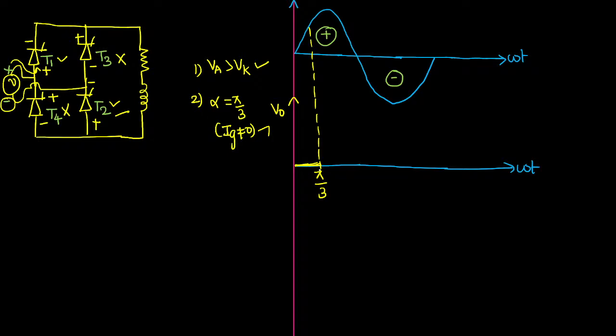After that, how can you observe the waveform? Will it follow the same input voltage? See, after 60 degree, will it simply follow the input voltage waveform or will the waveform structure be different? Here, if you observe the inductor, what is the nature of the inductor? We know V is equal to L into di by dt. Inductor will not allow instantaneous changes here.